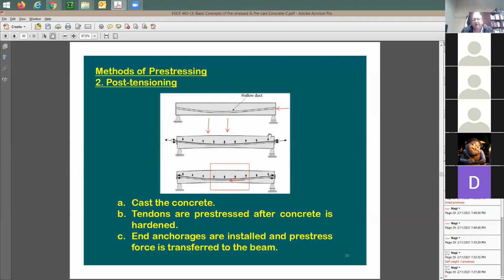And this is the theory behind pre-stressing. This is the idea behind it. Any given load wants to push the beam down, and now we're gonna try to balance this load by pushing it up. So at the end, deflection is gonna be controlled. You're gonna have a very small amount of deflection, right? And the stresses at the top of the concrete are gonna be much less.